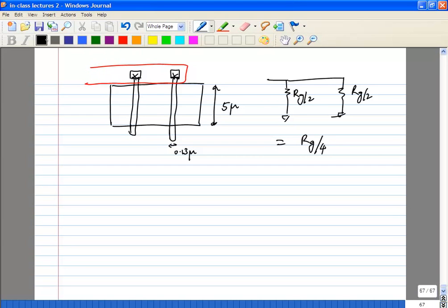Now the other thing to remember is, yes, there is a problem. The minimum size you are probably allowed to use, let's say in a 0.13 process, will probably be like 0.25 by 0.13. That is actually a very suboptimal layout, because when you increase the number of fingers, effectively this is actually two transistors in parallel. You will increase the effective amount of parasitics for each transistor when you go below a certain threshold for your width.